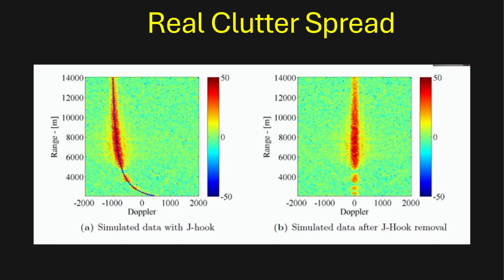So from what I've shown, it seems like these 2 methods would be sufficient, but in reality they are far from ideal, especially for very slow and very fast moving targets. One reason is that in real conditions, clutter will form a broad Doppler spread because of Earth rotation, error, and other factors. This creates some major challenges for slow object detection over very wide scenes that DPCA alone will struggle with. For small and fast targets, we need a better signal-to-noise ratio than along-track interferometry can provide, and ideally, we want to use some more advanced techniques for ambiguity resolution, sparse sampling, and knowledge-aided processing.